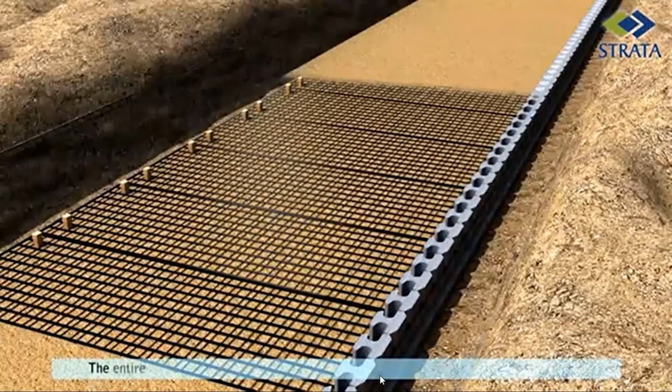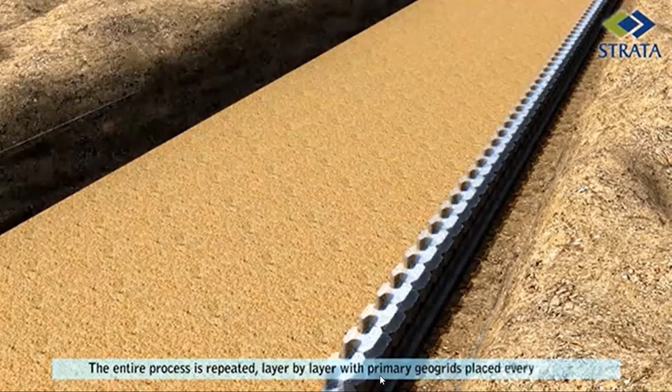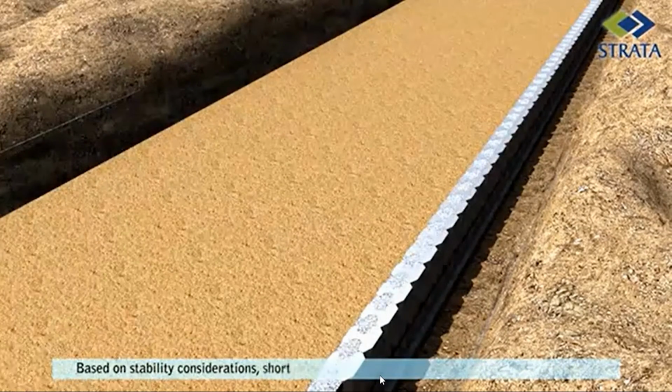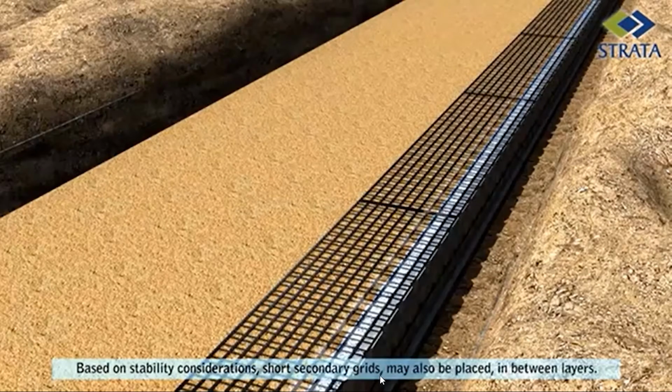The entire process is repeated, layer by layer, with primary geogrids placed every 3 layers. Based on stability considerations, short secondary grids may also be placed in between layers.